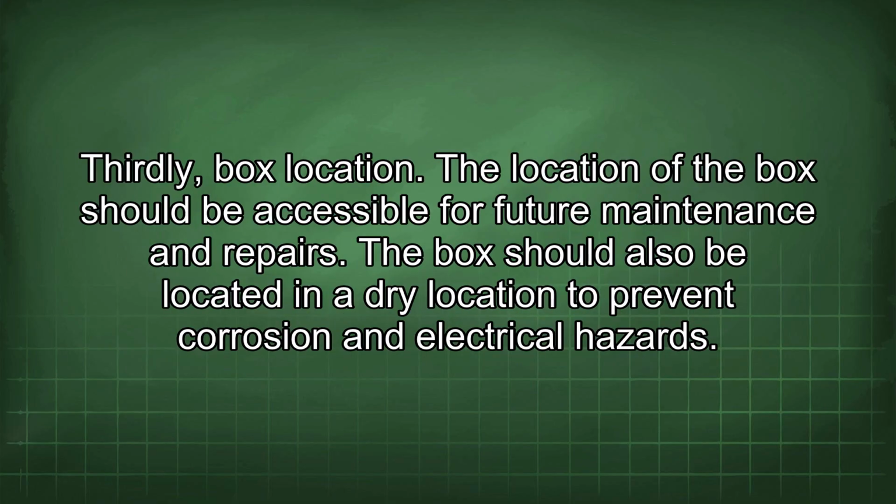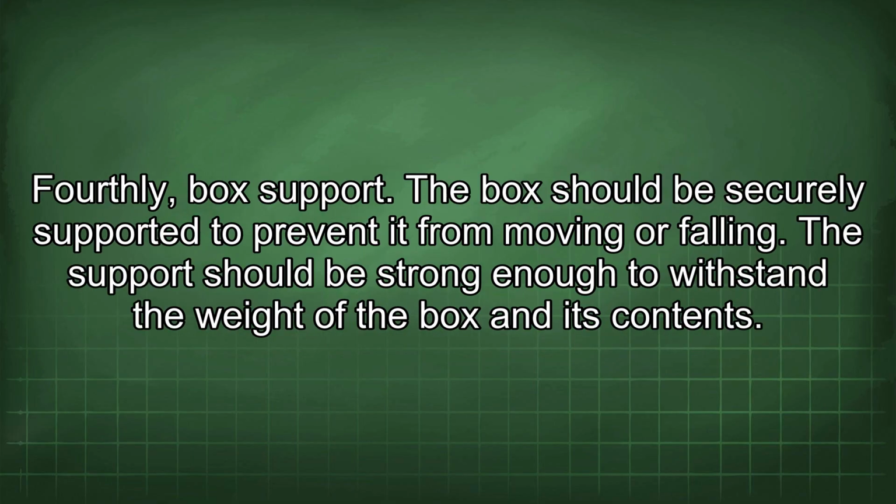Thirdly, box location. The location of the box should be accessible for future maintenance and repairs. The box should also be located in a dry location to prevent corrosion and electrical hazards. Fourthly, box support. The box should be securely supported to prevent it from moving or falling. The support should be strong enough to withstand the weight of the box and its contents.